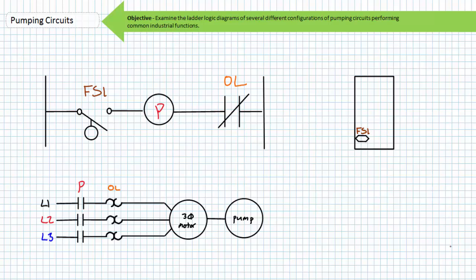3-wire circuits, in contrast, are ordinarily characterized by momentary manual switches like push buttons and a holding circuit. A 3-wire control circuit is suitable for applications where the unexpected starting of a motor would present a safety hazard. We'll examine both 2- and 3-wire configurations of motor-driven pump circuits.